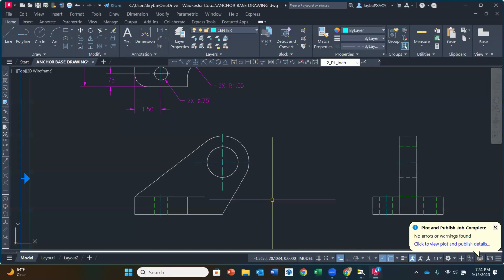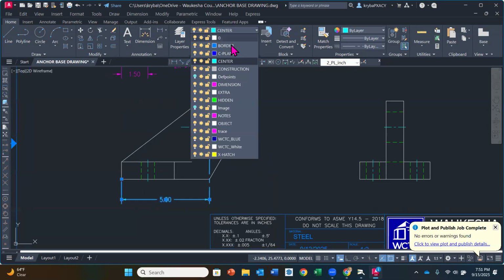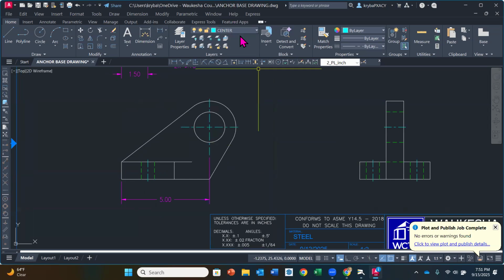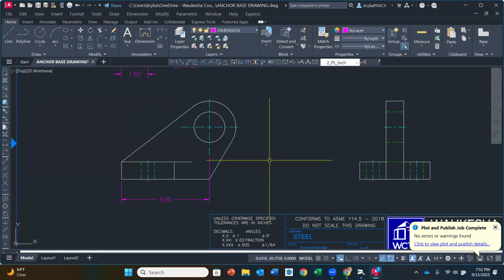So I'm going to go back to AutoCAD, and I'm going to do my linear dimension first from here to the endpoint of my, and you'll notice that, oh, I forgot to switch it back from center line. I did this on purpose to the dimension line. No worries. I just left click on it. I go up to my layers, I put it on the dimension line, hit escape, but then make sure you set the dimension layer as current.